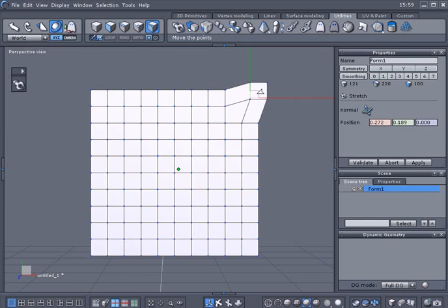Now I'm going to tap the space bar, but before I do, you'll notice there's a green and red ruler line by my cursor. That means there is no constraint and I can move in all directions. Now as soon as I tap the space bar, as you can see, I only got one color line or ruler line by my cursor. That is the horizontal constraint. I can move it right to left. If you see these two lines here, you would never really want to cross another line like that because you'd get some uncommon results.